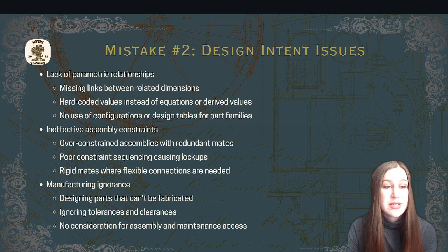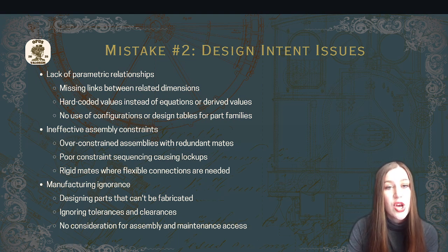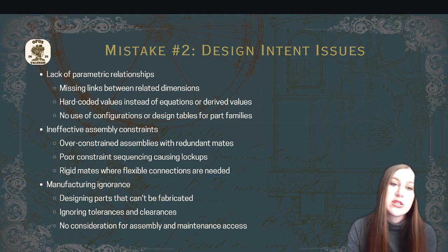The second most common mistake lies with your design intent. You may have a lack of parametric relationships, with missing links between related dimensions, hard-coded values instead of equations or derived values, or you missed using configurations or design tables for part families that you utilized.